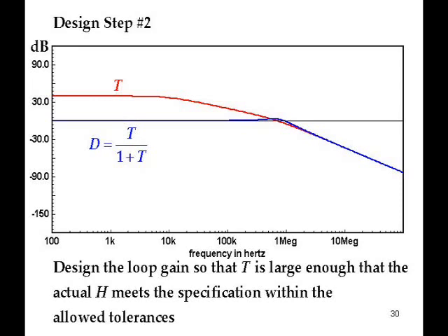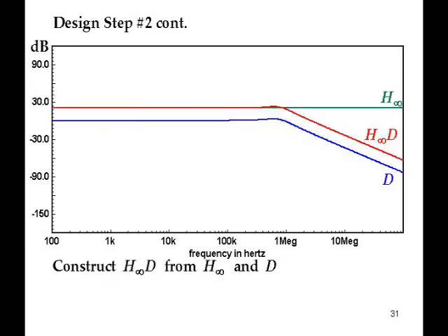And in this picture, which is actually an example that I'll be going into detail later on, notice that the D peaks up a little bit. Not much, but a little bit in the neighborhood of the loop gain crossover. And as you probably know, if that peaking up becomes excessive, that's indicative of too low a phase margin, and in the end, the peak goes to infinity and it's unstable.